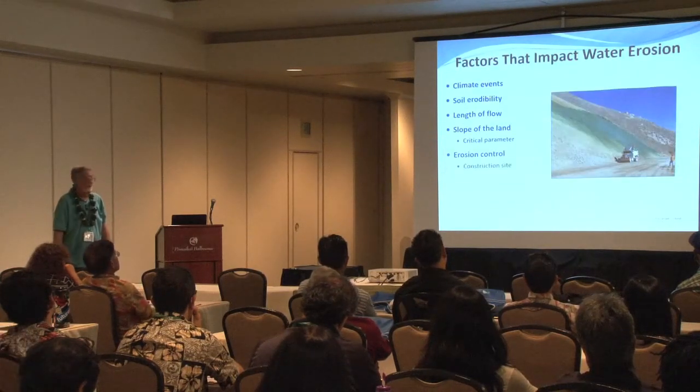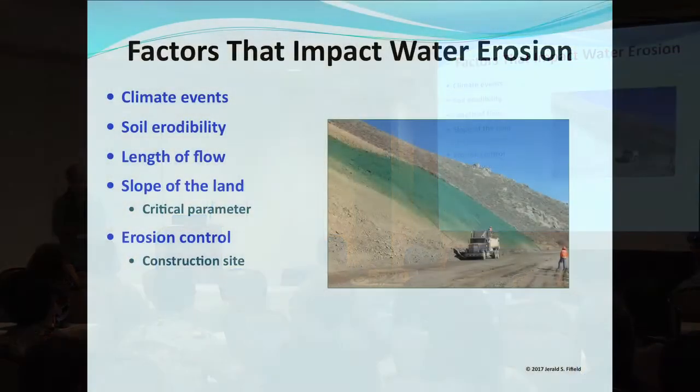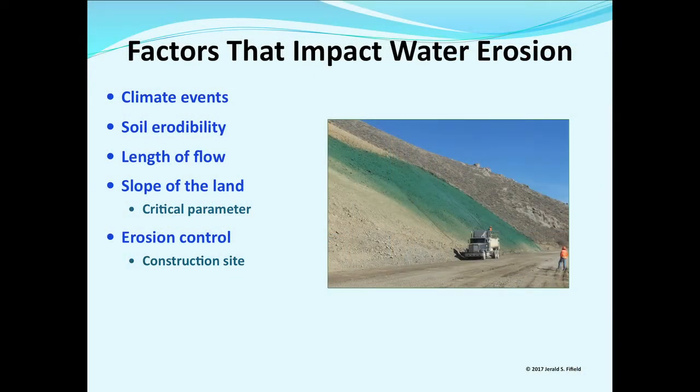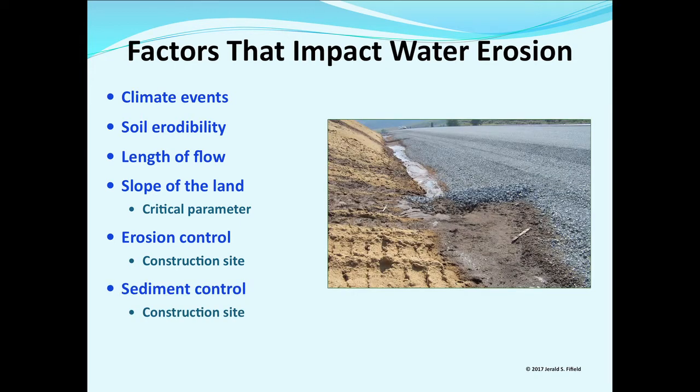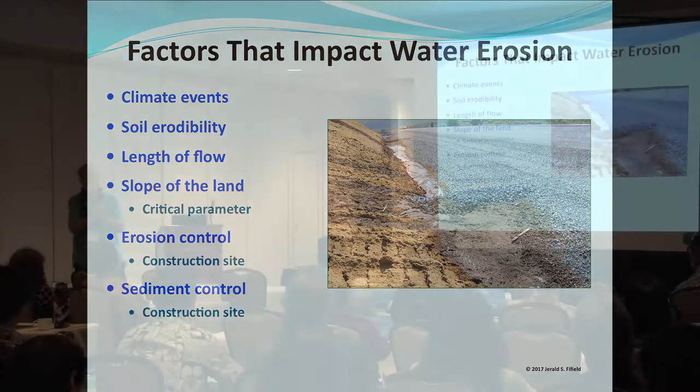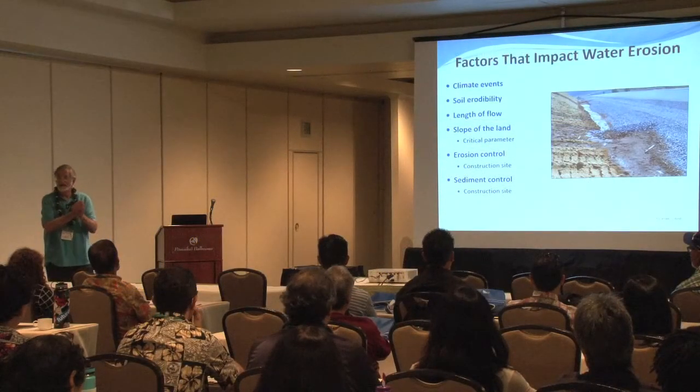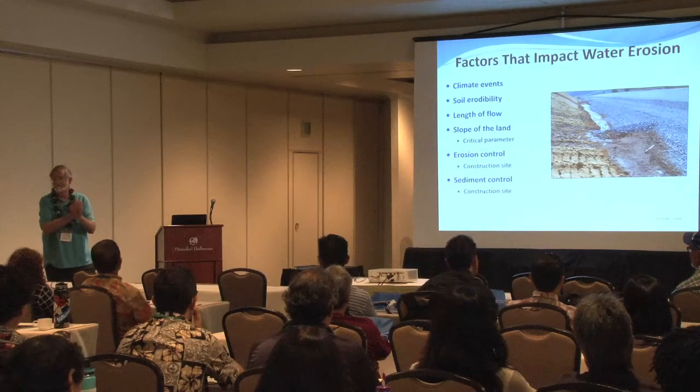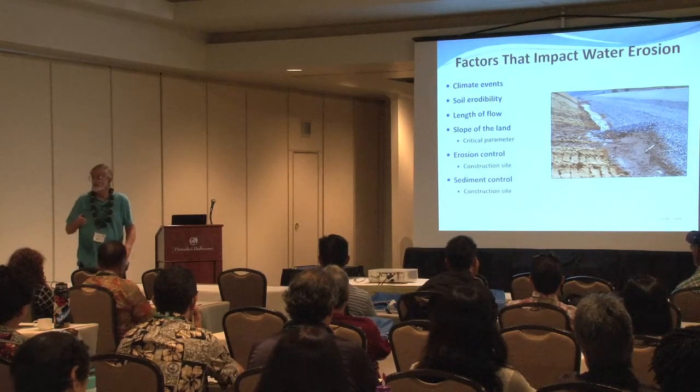That's a critical parameter. This is what you're trying to design your plans for. This is your BMP. What are we doing for erosion control? What are we doing for sediment control? Where do we put it in? How do we put it in? When do we put it in? That's the designer's responsibility, to work with the contractor. And by the way, I have another nasty thing to say. Designers, you should always go out to the construction site, especially when it rains. Find out what the real world's all about. It's different than when it's all dry.